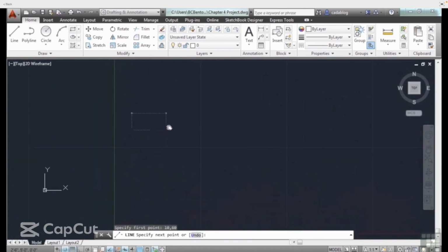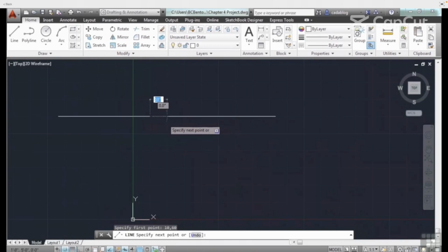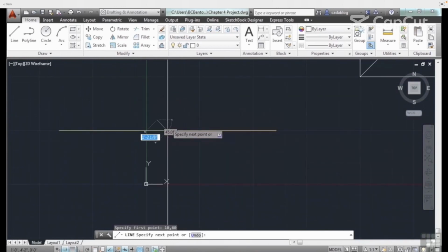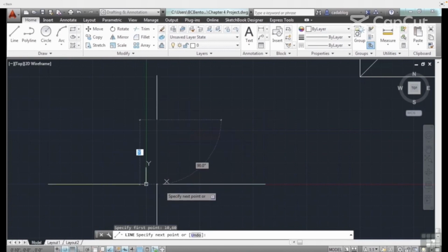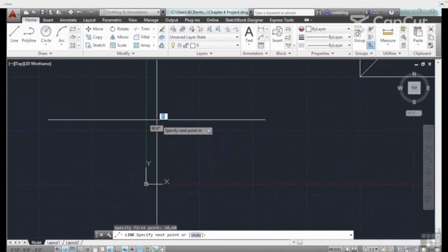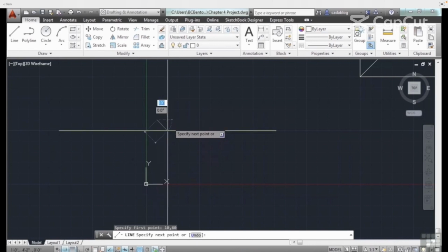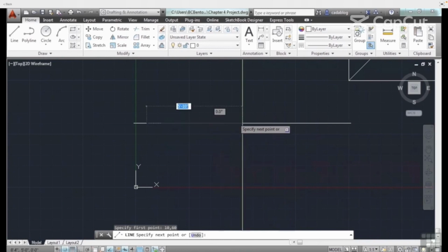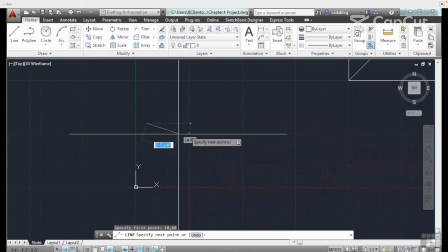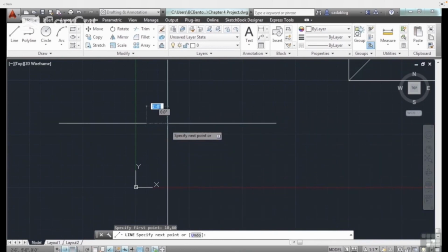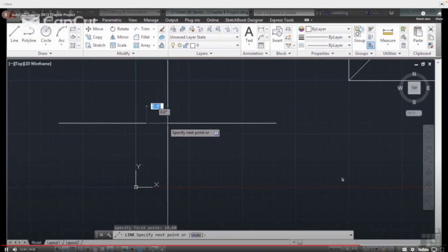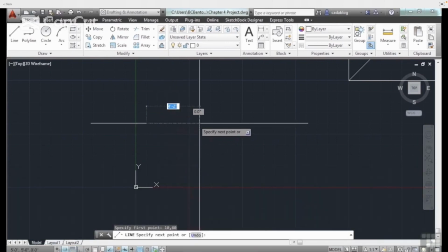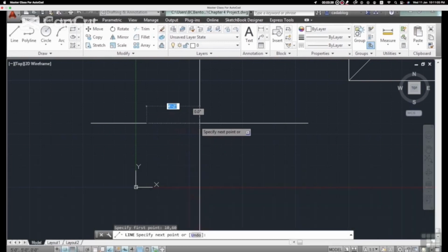So a coordinate of 10, which brings us right to this snap point anyway, is at 10 inches along the x-axis. And then a coordinate of 60 brings us up 60 inches on the y-axis. So that's great. So if we want to draw a line now that is 50 units long, well, we can snap to 5 different places here on the grid because we have set up our grid to be 10 units long, or